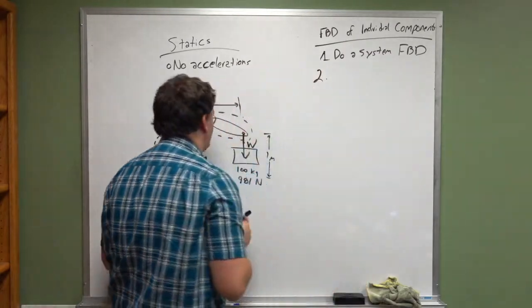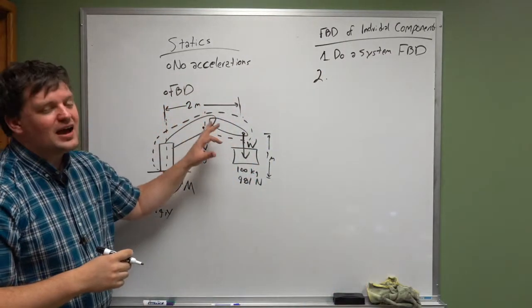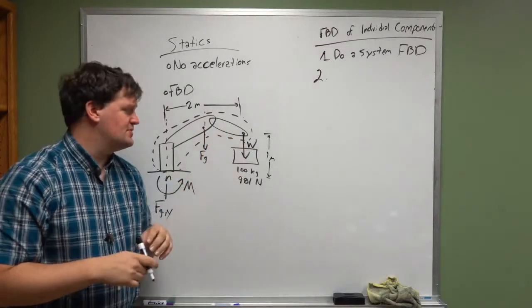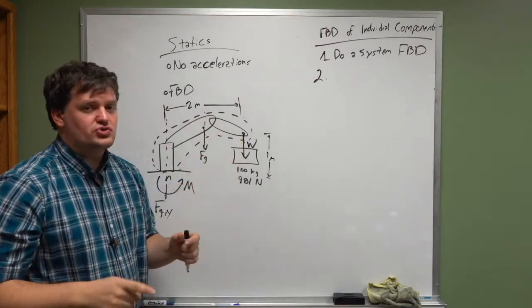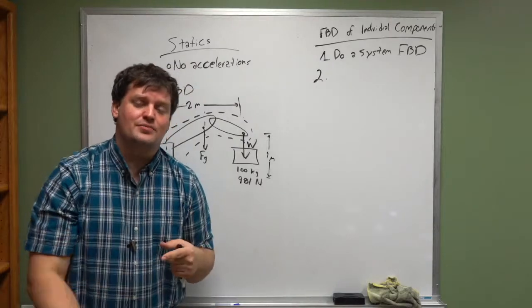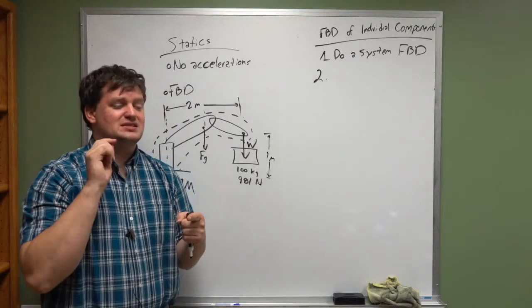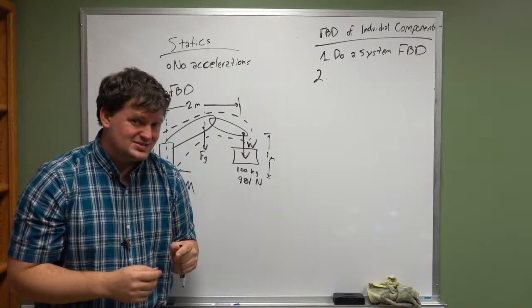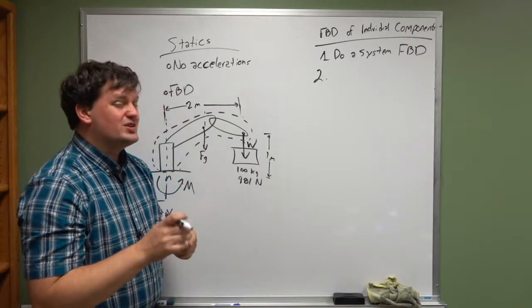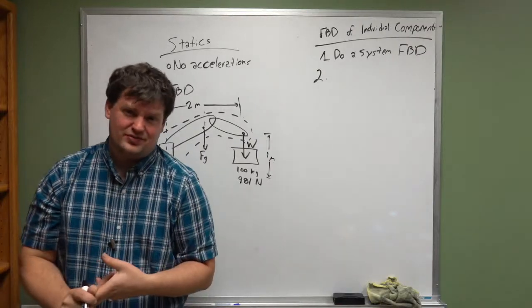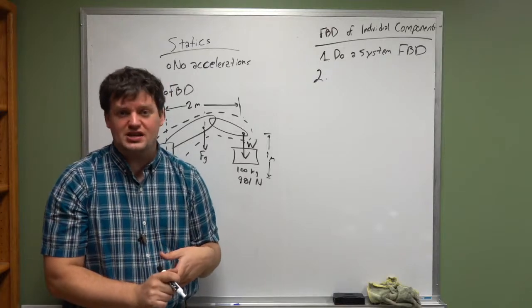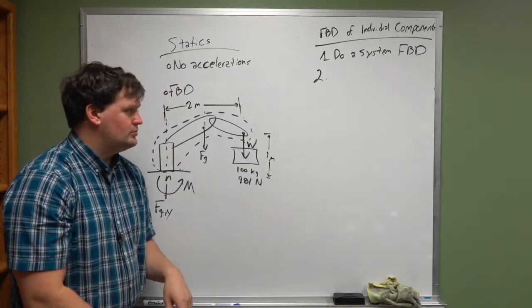Okay, so that matters for how forces are transmitted. If this is a string, strings cannot carry a moment. Strings cannot carry a horizontal force. Strings cannot carry a compressive force. Strings only work in tension. Okay?